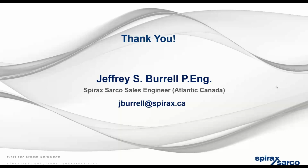Yeah. So also, Andy, I think the reason it might be working is maybe your back pressure is not as high. You still have enough pressure on your condensate line to move the condensate. But in scenarios where the back pressure is high and the condensate still keeps flooding inside your system during startup, you might get water hammer. And I've actually noticed it even in our lab here. When we start up, we get a little bit of water hammer, and we have to drain out the low points because our back pressure is a little higher than the warm-up pressure, right? So that would need to be done as well.